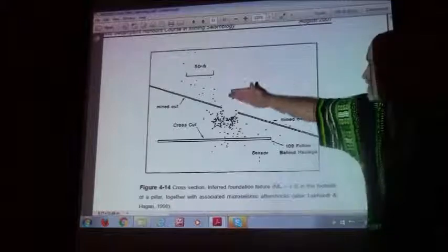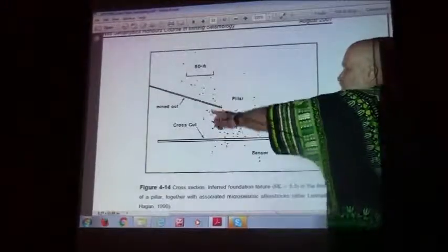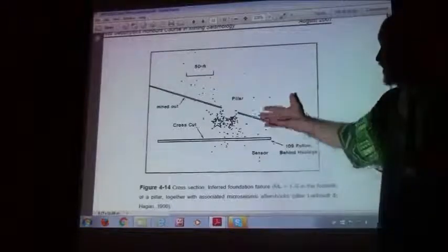And so what happened as the load came down is that your pillar punched into the footwall. It's a pillar punching event, and that's where your main event was, and that's where you've got a whole lot of aftershocks. You can see your pillar was actually sort of intact and pushed into your footwall. So we've got what we call pillar foundation failure. This is the kind of situation you are in: using your seismicity to understand how your whole rock system behaves.